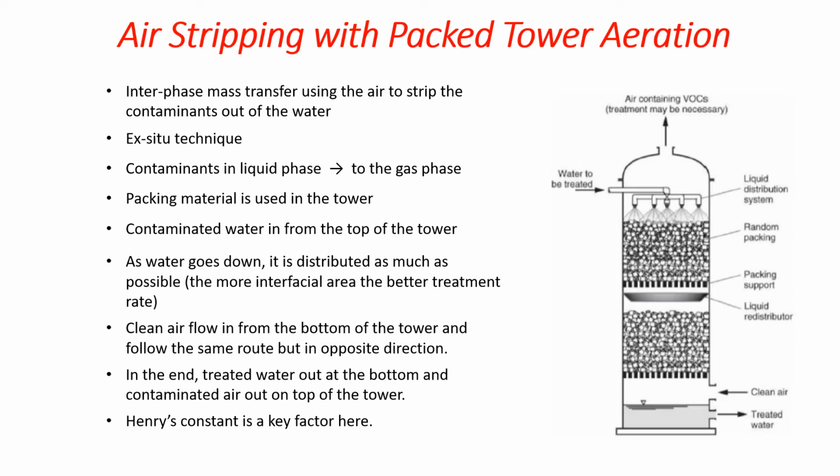As water goes down, at the same time, airflow is introduced through the same path, but in the opposite direction, which is from bottom to top, by air blower. As airflow is pumped through the tower, mass transfer from water to air takes place. We can say that Henry's law is the essential factor that controls this mass transfer method. It is used to quantify the concentration of contaminants in the air that was transferred from the water. In general, if Henry's constant of the compound is greater than 0.1, air stripping most likely works for this chemical.